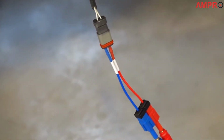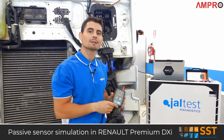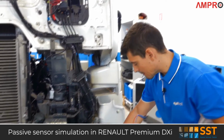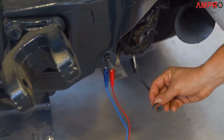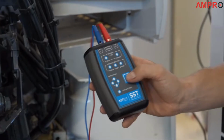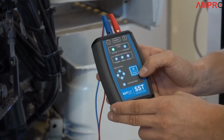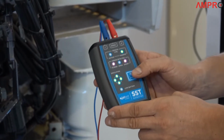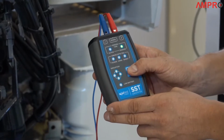After checking the correct status of the sensor, we want to send signals of an inductive sensor to the control unit from Jaltest SST. To do this, we change the connections to the control unit, and not to the sensor. We turn the device on, make 4 short keystrokes, and confirm the mode by pressing for 2 seconds.